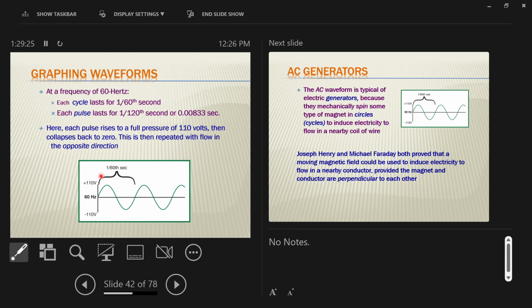So, one full cycle, starting at 0, moving through one entire positive pulse and one entire negative pulse and ending back at 0 gives us one full cycle, one full wave, 1/60th of a second. Half of that distance, right? One pulse width of distance is 1/120th of 1 second.